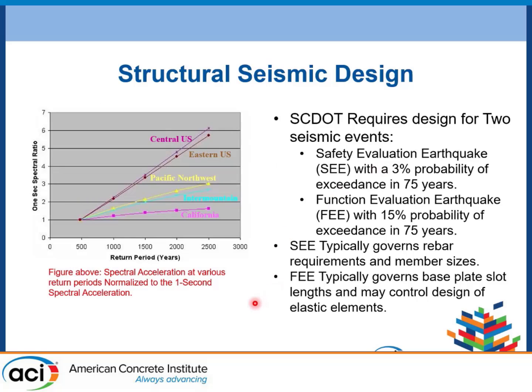Lee Marsh mentioned a minute ago some of the reasons why some states, in particular South Carolina, evaluate the 2,500-year event. South Carolina does design its higher demand requirements against the 2,500-year event, so the safety evaluation earthquake that has a return period of 2,500 years.